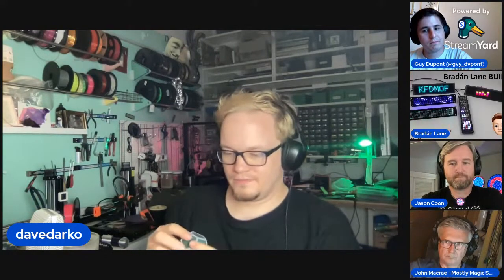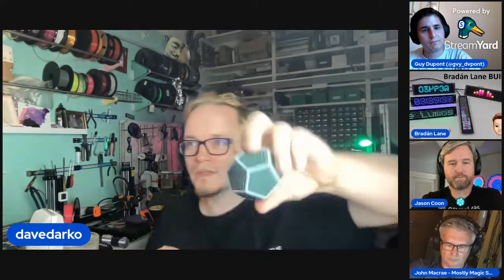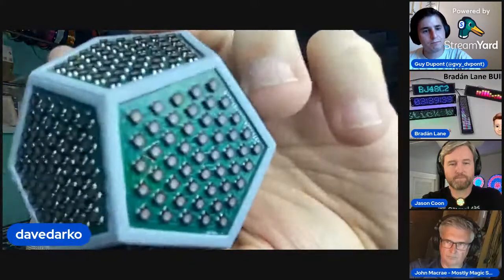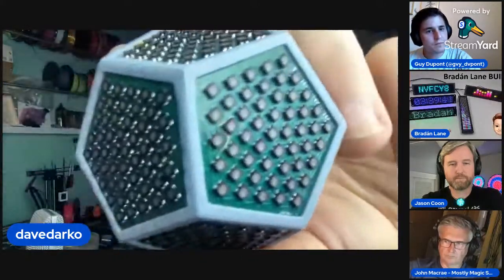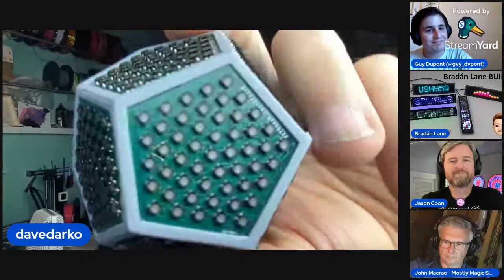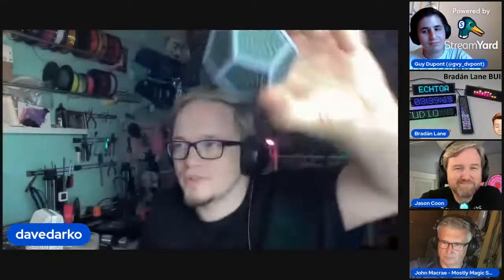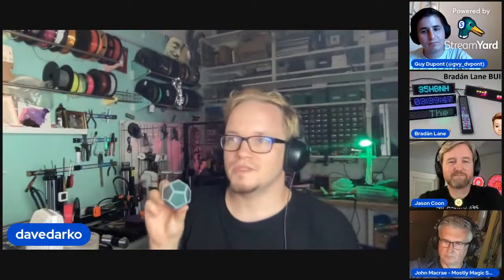Yeah. Did I turn it off? Yes. There is also a little botch wire, and I had to put that in on all the PCBs because I forgot to route one LED pin. Yeah, and so that's why one LED wasn't glowing at first.